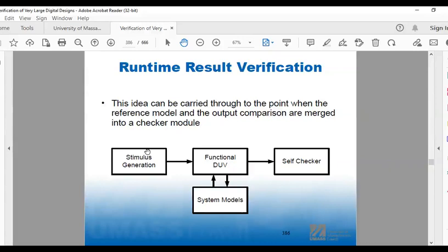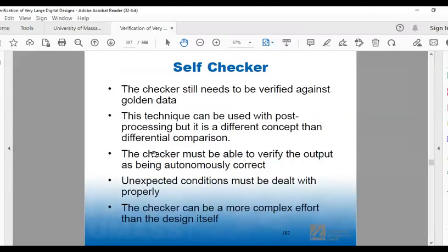Complex stimulus, by the way, is stimulus that knows what the result was. Maybe it just needs to know what it's done, but it needs to know something about it. So there's really no such thing as simple stimulus. I think if I had to give you one example of simple stimulus, it would be clock and reset. But everything else, the stimulus has to know something about the state of the system, and the response definitely has to know, especially in a random, constrained random test, the response checker really needs to know what's going in. Maybe my MATLAB example, where it generated a whole bunch of data and then knew what data would come out, that you could do that in this simple way. But there's got to be some feedback and feed forward in this process.